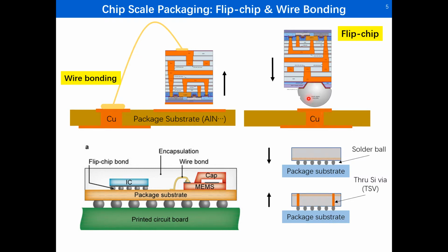At the beginning, only when the chip is inverted would the solder ball be used. However, afterwards, with TSV, the die can be connected to the substrate by solder balls even without being flip chipped, but this method will also be called flip chip.